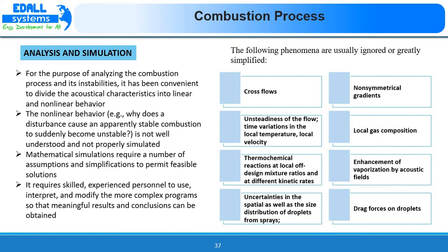Cross-flow, then non-symmetrical gradients, then unsteadiness of the flow, which includes time variation in the local temperature and local velocity, then local gas composition, thermochemical reactions at local off-design mixture ratios and at different kinetic rates, enhancement of vaporization by acoustic fields, uncertainties in the spatial as well as the size distribution of droplets from sprays, then drag forces on droplets. So all these phenomena are being ignored when the nonlinear analysis is carried out.